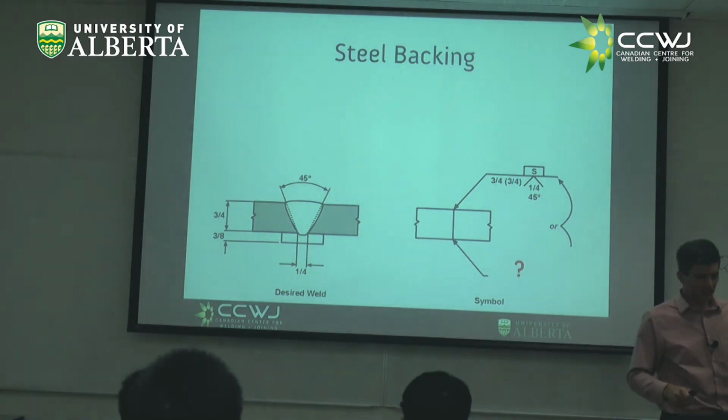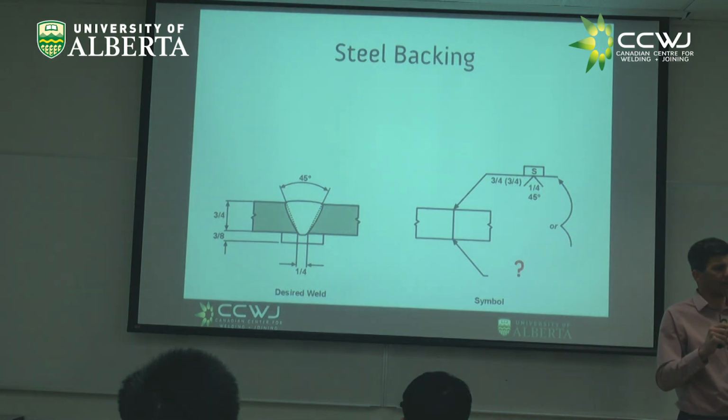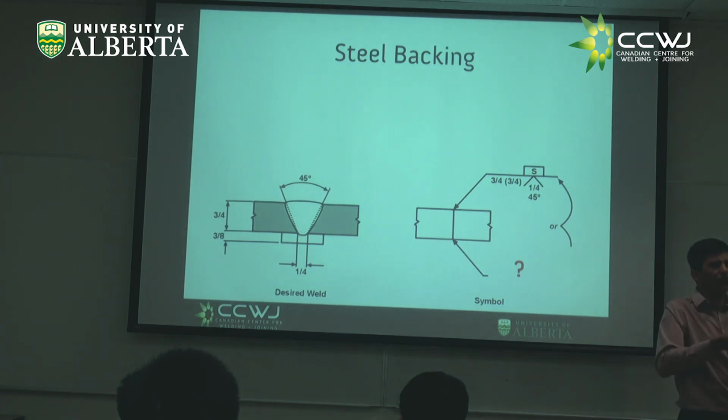But sometimes you might have a partial penetration weld, right? You say what groove you want to have, and you want to melt more than that groove, right? So you have to specify what groove preparation you're going to have. This is the groove preparation, and this is how much penetration you actually want, right? Those are more sophisticated things. They are all explained very clearly in the standard that you have direct access to.